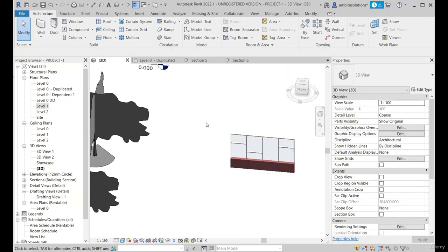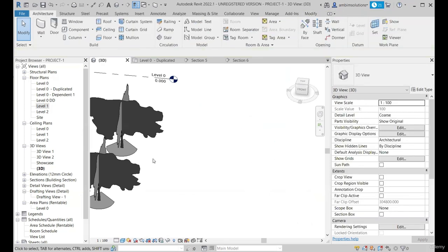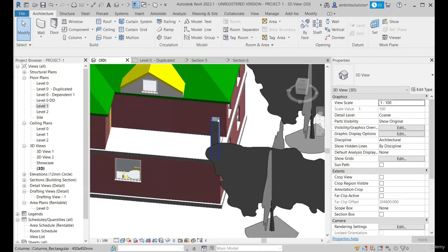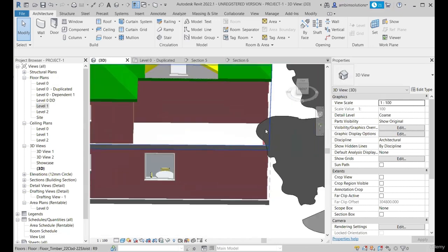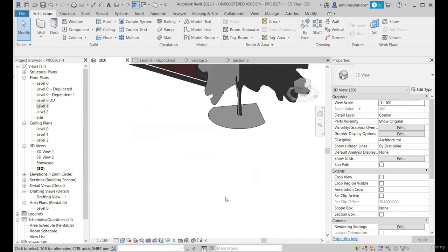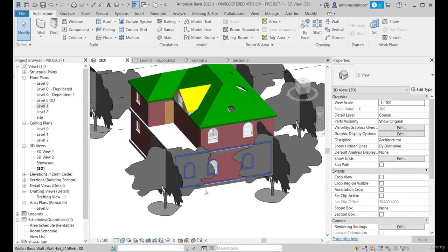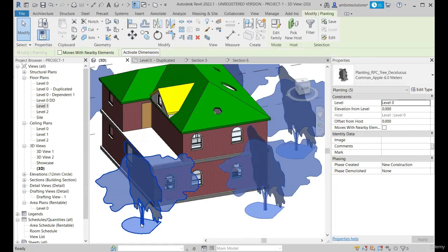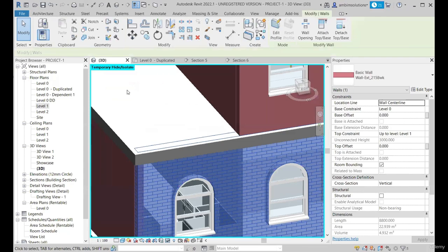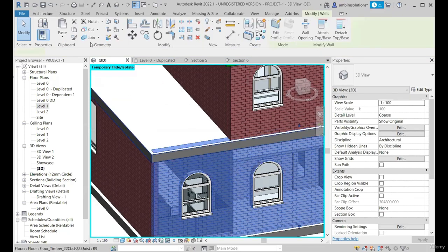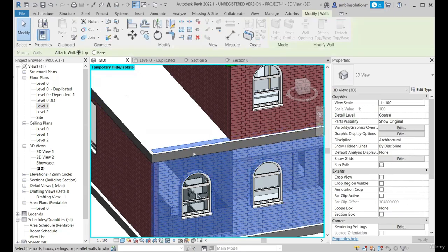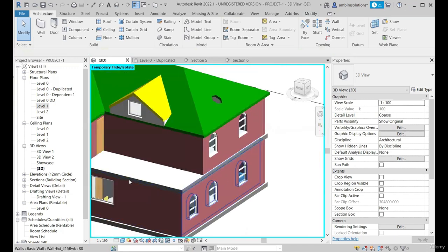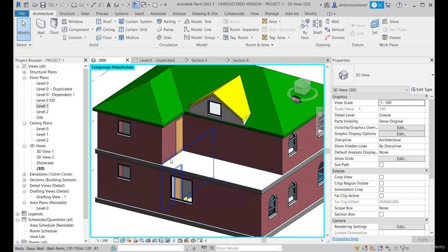Now let's take an example of creating a mullion in the project that we are creating. Let's delete this column, there is no need for it. We can create a curtain wall on the first floor here. For now, let's select and hide these trees, and join geometry them, or maybe attach top. Now we can place a curtain wall along the edge of this floor.